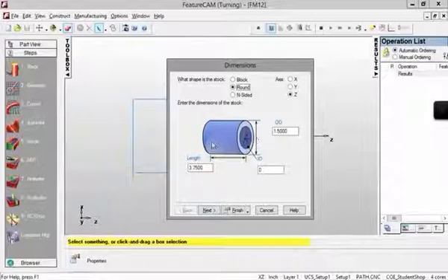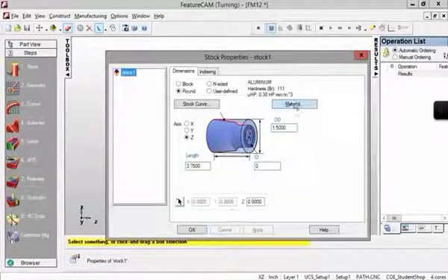As we already know, we are doing the lathing, and the raw material should be a cylinder. And so in this way, we select round, and since it's a cylinder, the inner diameter should be 0. And the outer diameter we use 1.5, and the length is 3.75. Okay, click finish. We can set up material here, and the program reference 0.